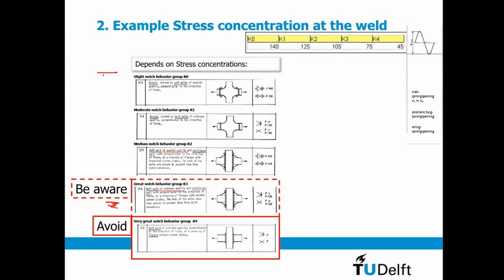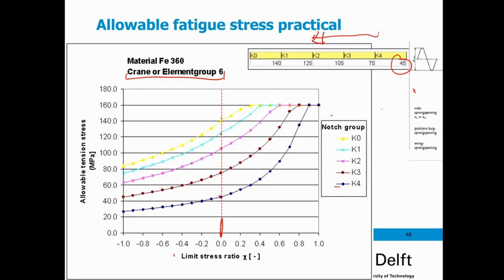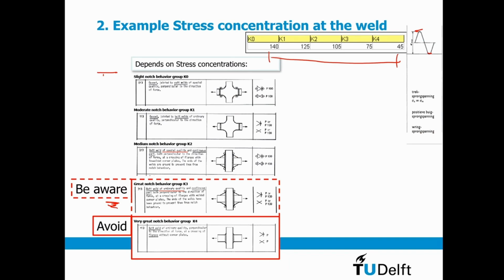Yeah, and again, here you can see the allowable stress if you have zero stress or a maximum value. And if you have, of course, this situation where you have tension and compression at the same level, this value drops to, let's go back to the curve. This is here 27, this is 45, 63, and especially this one: 27 megapascals as allowable stress. That is really, really low.